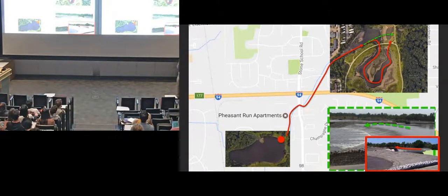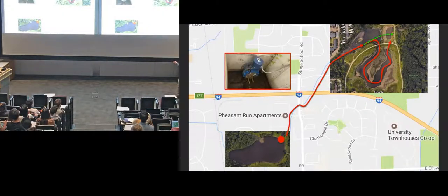So what we try to do is basically say, well, could we control this? Could we just put a sensor downstream that's measuring the levels in that wetland and only send down water when it has capacity? So we're controlling the valve upstream and only sending water down when there's room. It's not like an earth-shattering concept. You're just opening a valve when somebody's telling you they got space, right? But again, it's across the span of a couple square miles, and it's a bunch of students doing it.